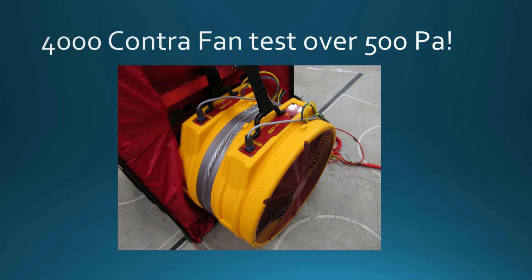One way to do that is simply to measure the enclosure leakage, then put plastic on the ceiling, as someone is doing here, remeasure it, and the second measurement is the hole in the bottom of the enclosure, which allows the heavier than air agent to flow out. This takes a lot of time, and if you have any leaks in the plastic at all, it doesn't work.